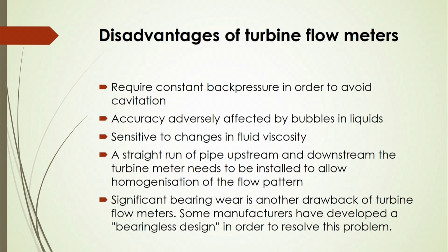And also you will see some manufacturers have developed a bearingless design in order to resolve this problem of wear in the bearing. So, these are some disadvantages of these turbine meters, and generally it is being used for large scale operation of this fluid flow phenomena and measuring the pipe flow in industry, that is, to supply, suppose, liquid on a mass scale, and in that case you have to measure the flow rate by